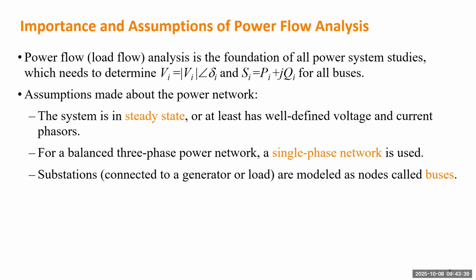But in power flow analysis, we don't go into the detail of each substation. We treat a substation simply as a node, or a better word, a bus. Bus means it can deliver power or receive power in many directions, so you can connect many lines to the same node. Think of a node as a dimensionless point, which is not accurate. The bus itself in a power system can be another, smaller scale power system, but usually we call it a bus.